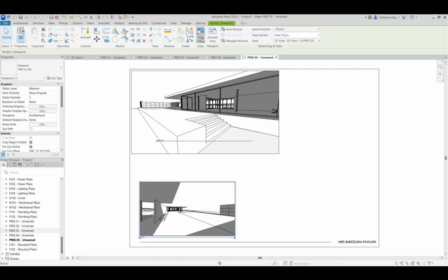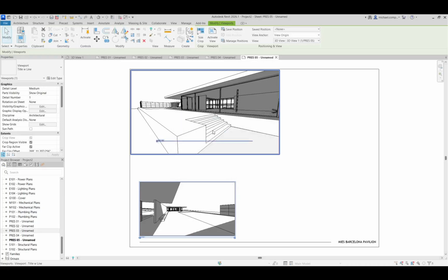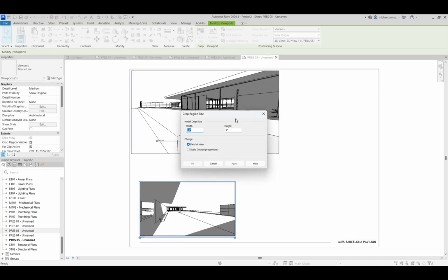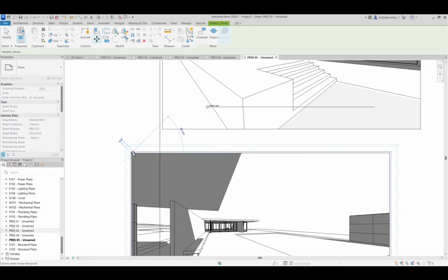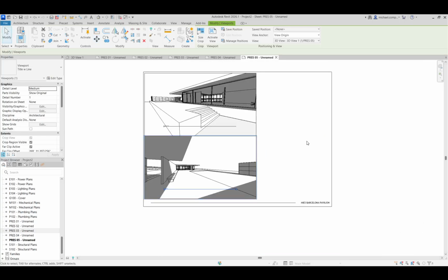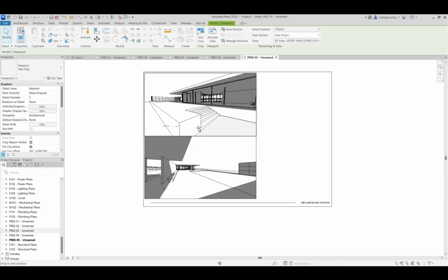I'm going to do the exact same thing. So scale 14 inches. Oh, wait, that didn't, what happened? Scale 14 inches. There we go. Apply OK. Now, these will snap if you move them, if you want them to. So I'm going to snap up to that corner and then change both of these to just title only, no lines. I'm going to move that title over here and then move that title over here.